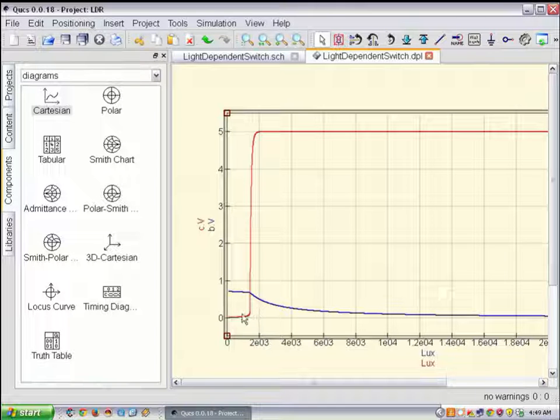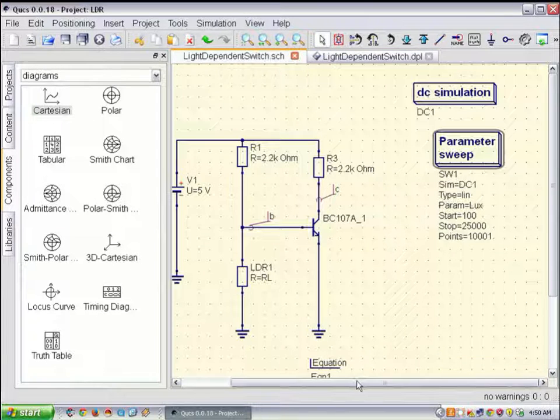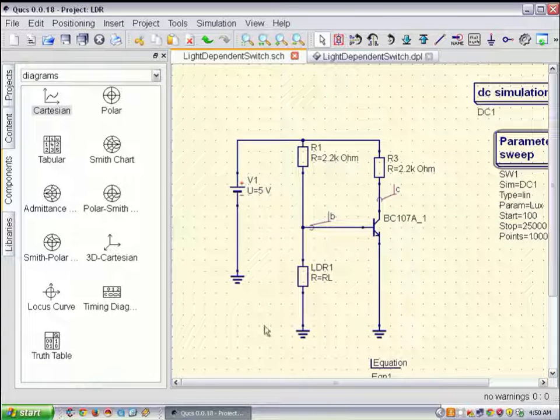So it is switching on when your light is, let us say, at the evening level. So at 5 o'clock your switch will turn on. So you can use this circuit to turn on something, say, turn on a light when it is dark, or it will turn on the security light when the door has been closed. So you can use this circuit to respond to the variation in light. Now this becomes a light dependent circuit.